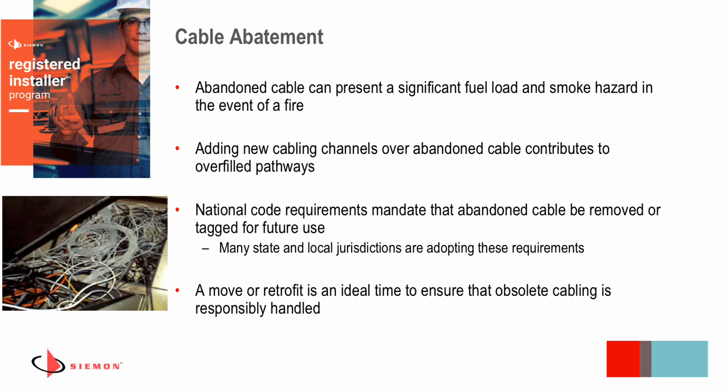The NEC does require that any abandoned cables are removed or at least tagged on the ends for future use. And you can find, obviously, local authorities having jurisdiction. Those local requirements will supersede any national ones, but most of them have adopted that as well. So if you have a customer who's looking to upgrade their cabling plant, it's good to educate them on that, because not only is it something that they need to comply with to remove any legacy cables, but it also provides a revenue opportunity for installers to do that work.